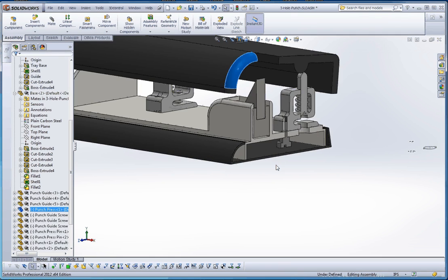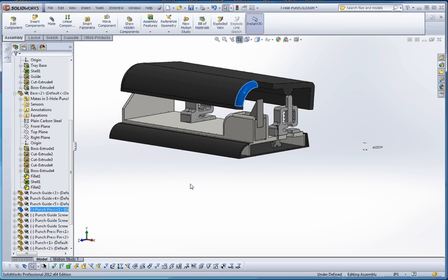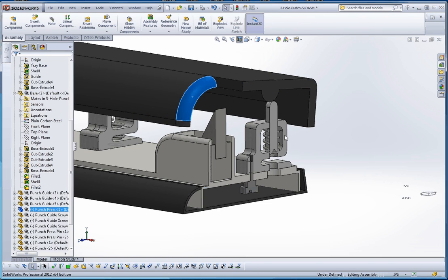So I think this model is in pretty good shape. You've done a really good job on this so far. It looks really realistic. I would make those changes that I put in there. And remember to have good, robust sketch geometry in order to manage the parts that you're making. Plus, when you get into the assembly environment, remember to fix the first part to your origin. Not just fix it in there arbitrarily, but make sure it gets fixed to the origin, and everything else should come into place. So if you have any additional questions, let me know.